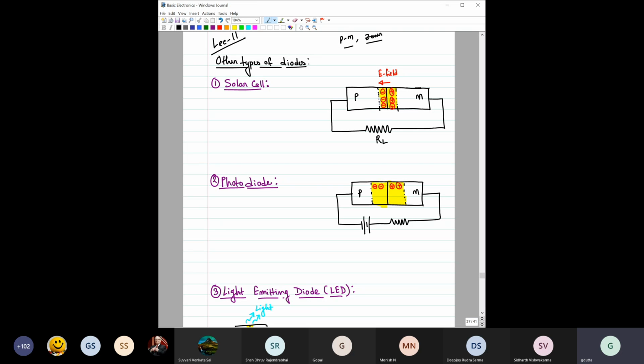So this solar cell is basically a PN junction. You can see this PN junction connected with a load, represented here by a load resistance. When you form this PN junction, there will be a space charge region, or depletion region, with mobile charges, positive and negative, on either side. There will be an electric field directed from the N side to the P side inside this depletion region.